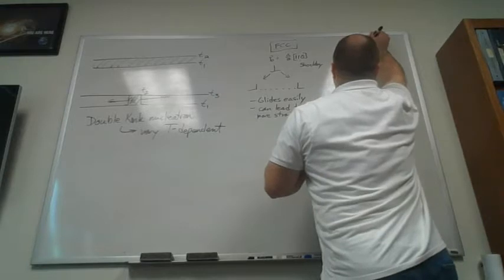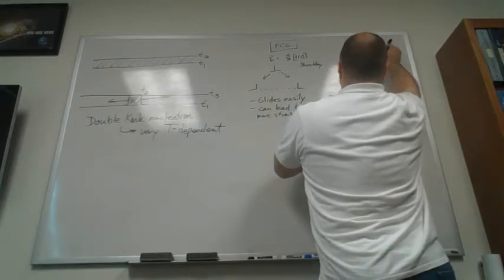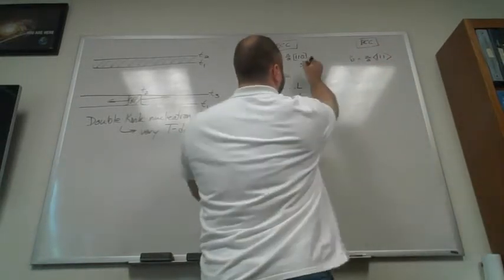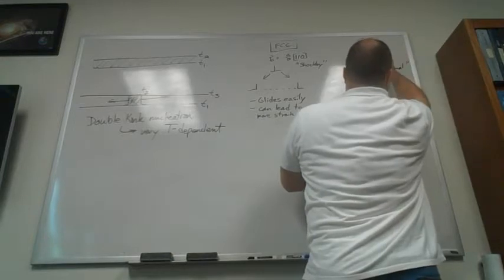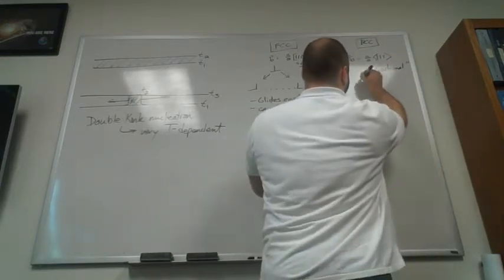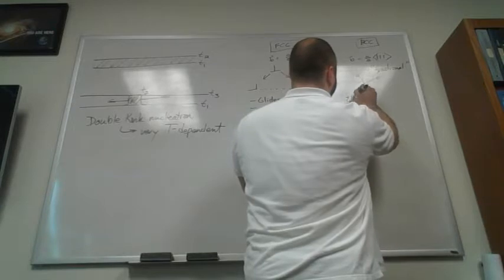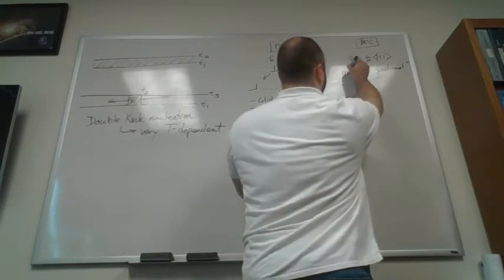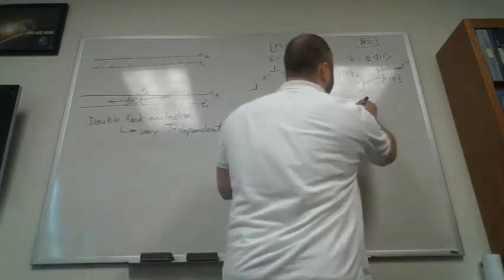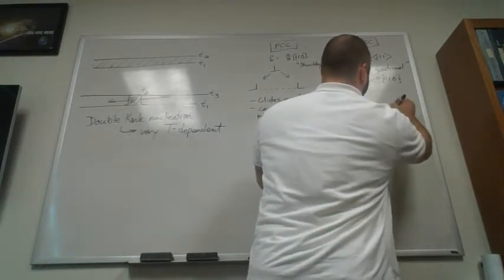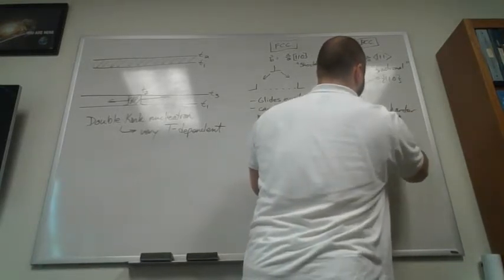So BCC materials, on the other hand, have a Burgers vector of a/2 <111>. But instead of these Shockley partials, we end up getting these fractional dislocations. That's the complication. And you can think of it as some sort of threefold splitting off onto different {110} type planes. Okay? And the main effect is that screws are harder to move by glide. Okay?